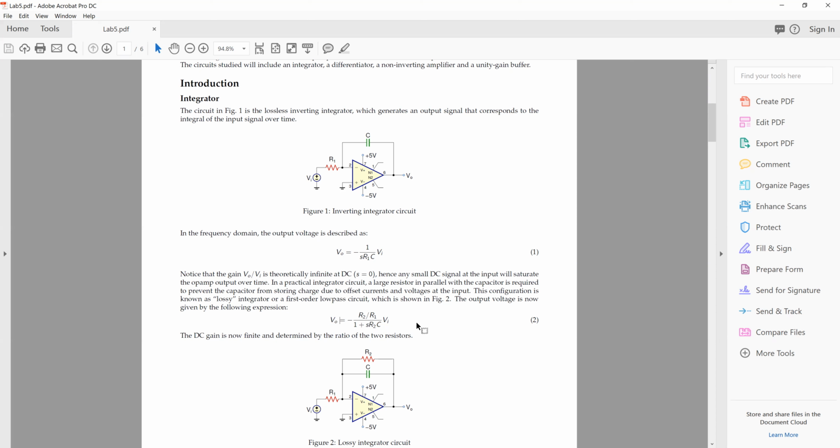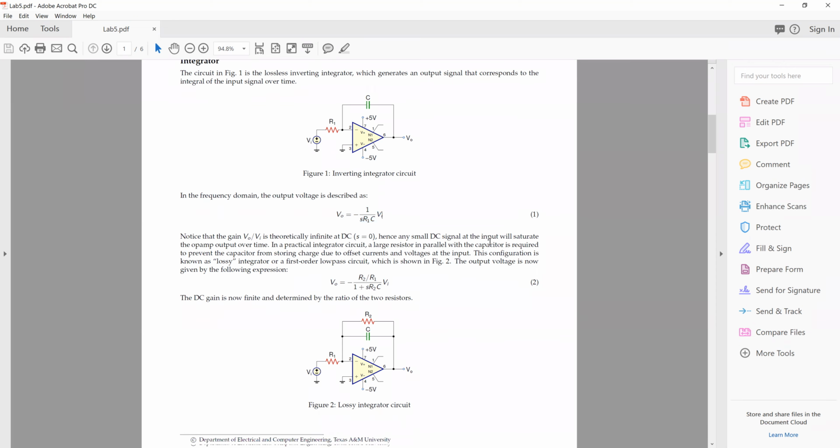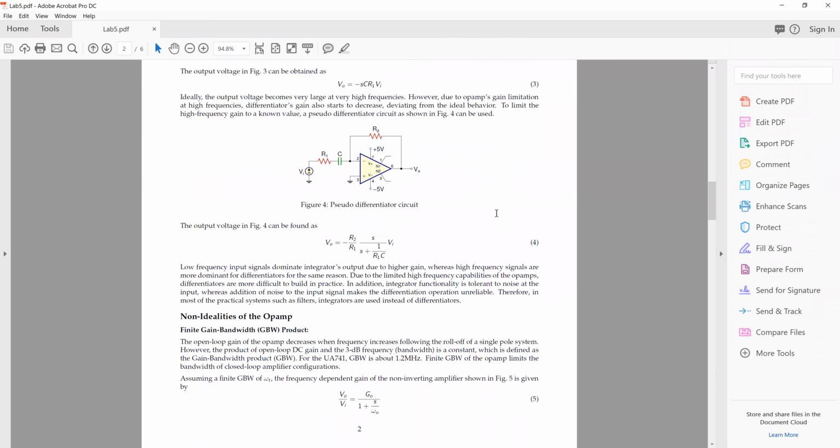What I would recommend is that you make an approximation saying you're operating this at high frequency, so that this transfer function looks like this transfer function. And I already explained how this one looks in the time domain. It's just the integral of the input with some constants multiplied. So you can either say it will be an inverse Laplace of this, or you can say this, and then the time domain is just the integral of the signal. That will be your first question.